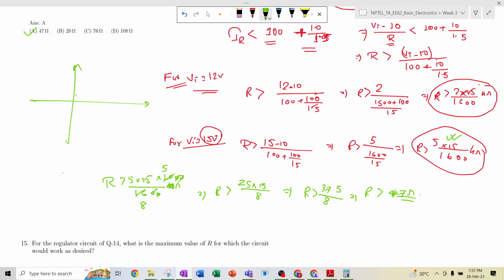Suppose in the diode characteristics we have seen, this is the IV characteristics. The current becomes very high after its cut-in voltage, that is 0.7 volt, and it is very low in reverse bias, and then suddenly at the breakdown voltage the current becomes very high, right? So we can refer to this as the breakdown voltage. Ideally, in breakdown,